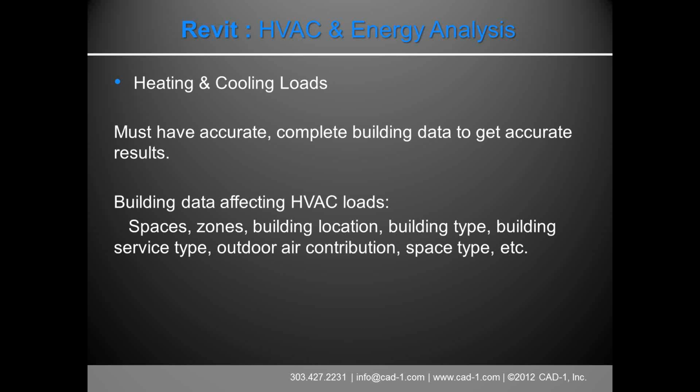Some of the things that are going to affect your HVAC loads are the spaces. You need to have spaces in every space, including plenums, attics, basements, anything that's enclosed by the building, whether it's heated or cooled or not. Zones, you want to have the zones in there. There's not a lot of information with zones, but they need to be in there. This is where you get your outdoor air information, which can definitely affect your loads and your analysis.